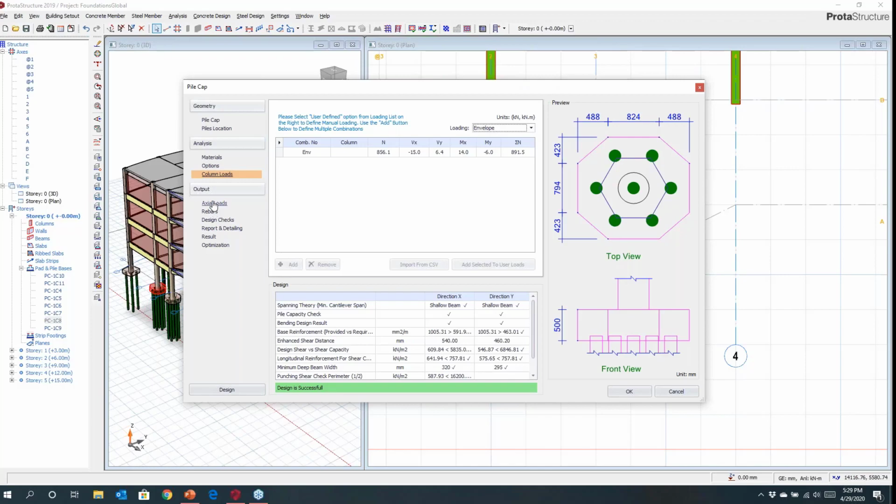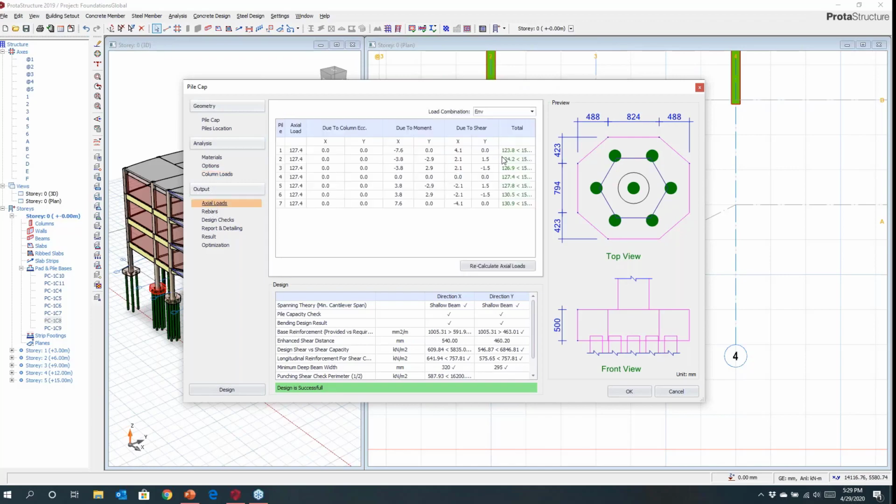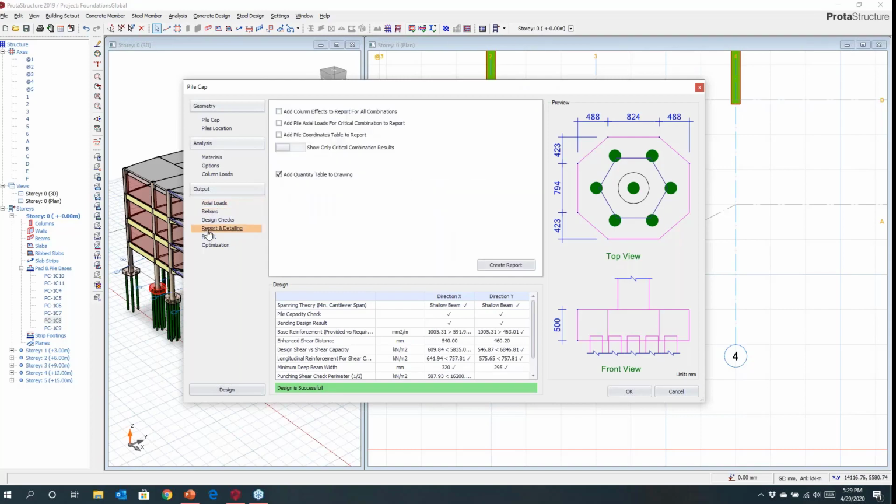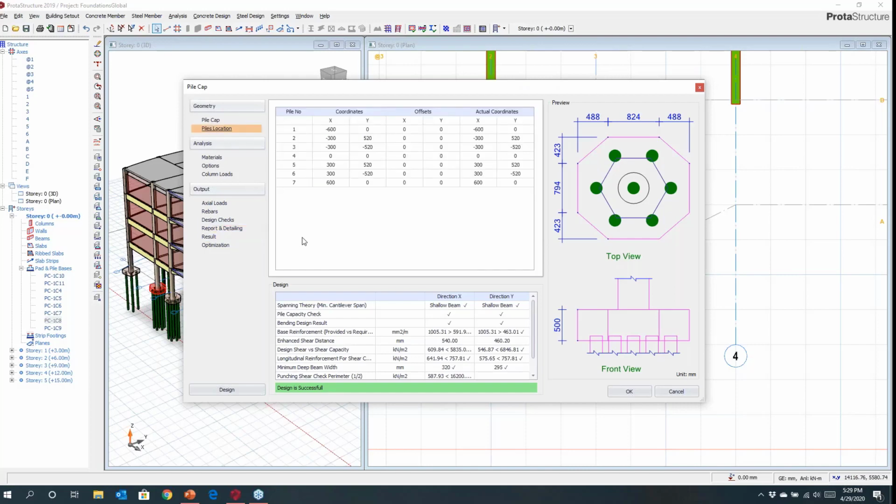Okay, so we will then check the pile capacities against allowable. So if anything's exceeded, you'd see this here. And we will then come through and perform different design checks to ensure that the results are designed. Now, which is often the case, you're on site and you may find that piles don't actually end up where you want them to be. You can move these around.